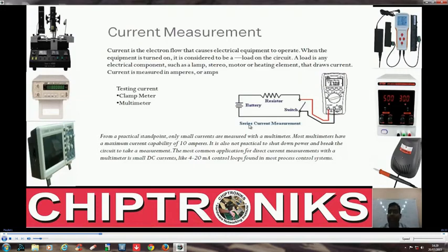So if we are going to diagnose any circuit, how can you diagnose it? You have to measure voltage, because voltage is always fixed. Whatever type of application you are running, voltage is always fixed. And as I said, we measure current when we find a situation where all the voltages are exactly coming, all right, but the device is not operating normally.